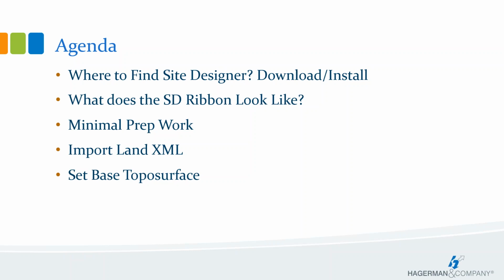Before that, we will find where to download, then see what the ribbon looks like, some minimal prep work, import Land XML files, set the base topo. All the while, I will sprinkle in helpful tips to get you over those initial stumbling blocks. Then we will start to take a look at the tools themselves and how to modify the features you placed if needed.